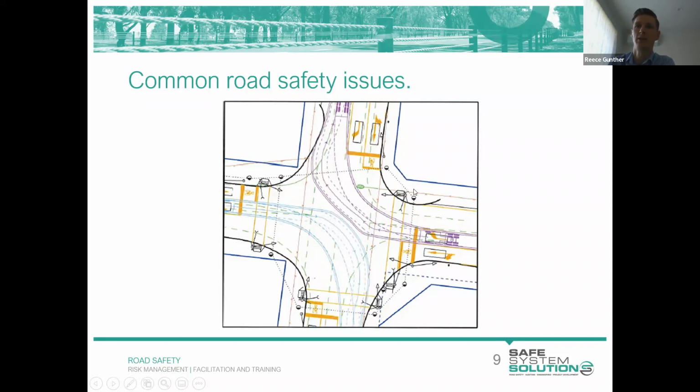But we'd assume, being a signalised intersection, that there's peds around, and for a pedestrian walking along here to make the turn to go down the minor leg, you have to step off into the traffic lane and then back on to the footpath in that direction, putting himself at risk of being struck by a vehicle. So that's a great pickup from you guys.